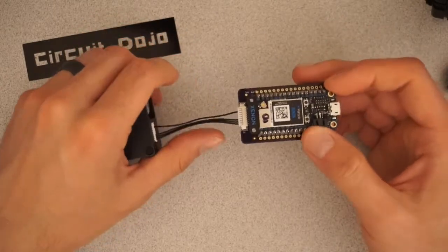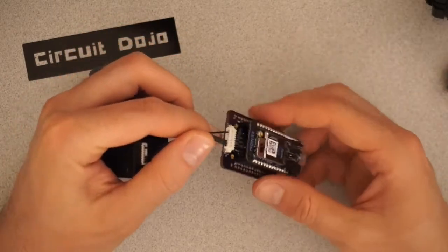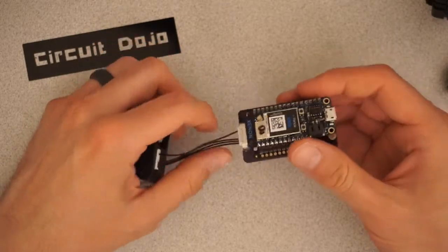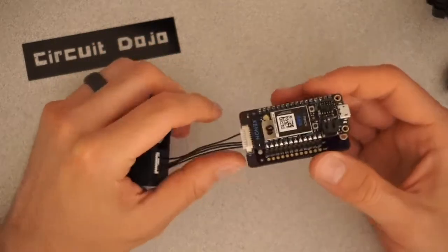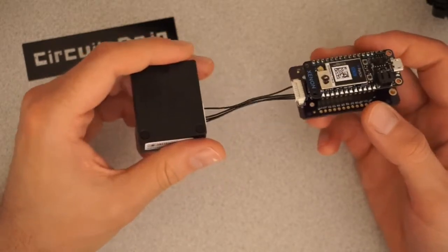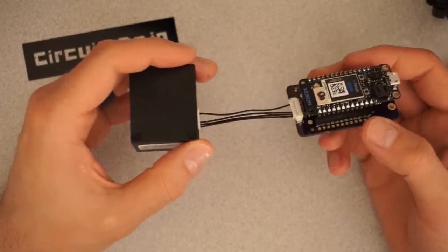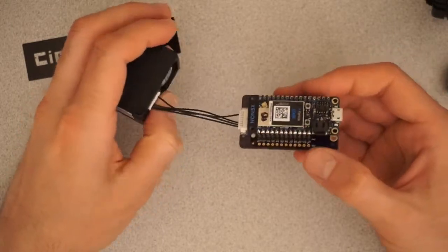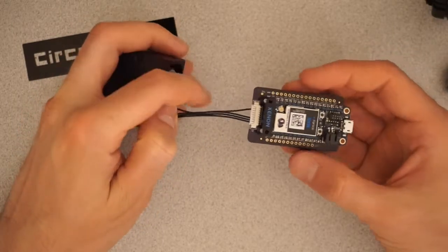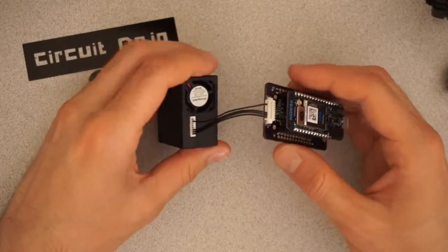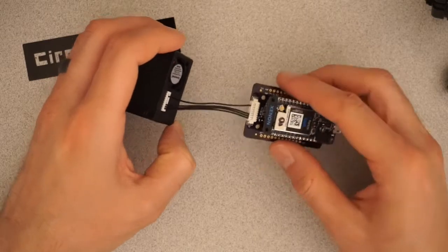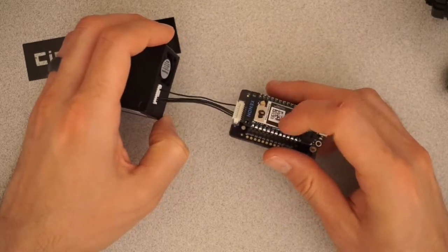The Xenon boards actually have two hardware UART interfaces. The Argon and the Boron only have one. So remember that if you are using the setup with an Argon or a Boron, it only really matters if you're starting to interface or work with other sensors that are also on UART. The Xenon has two because it doesn't have any external radios.